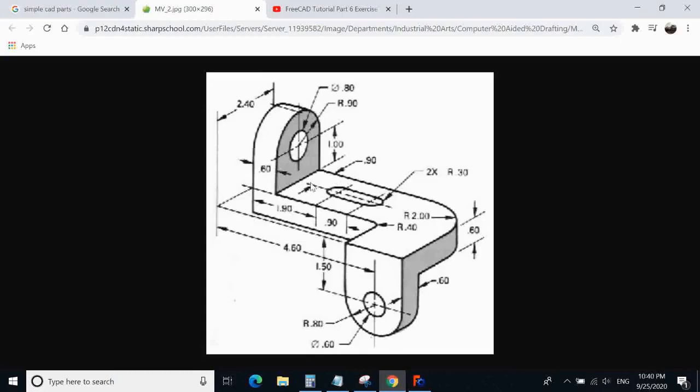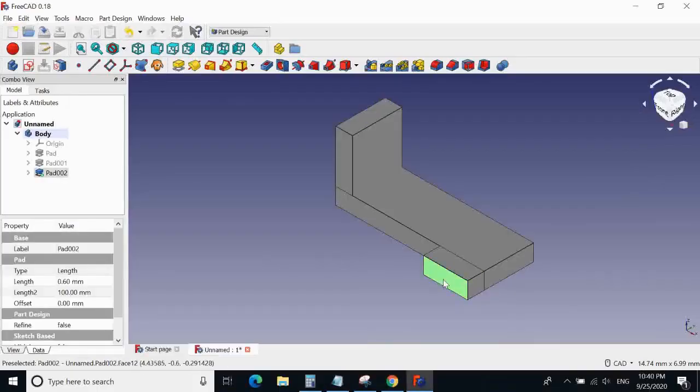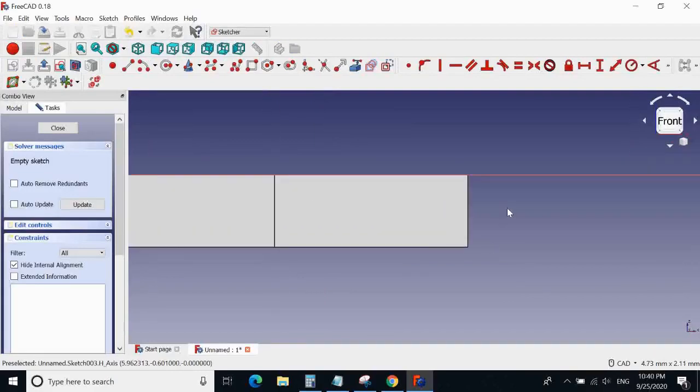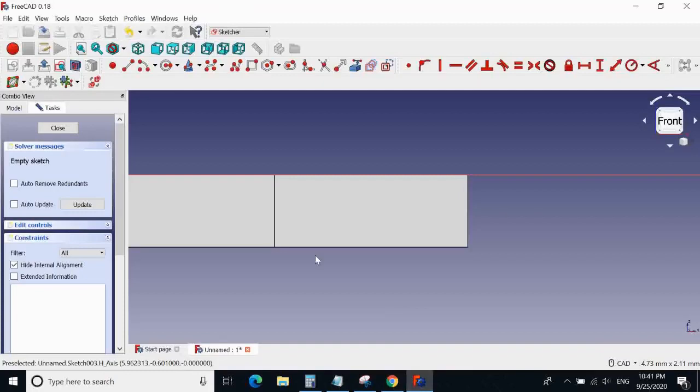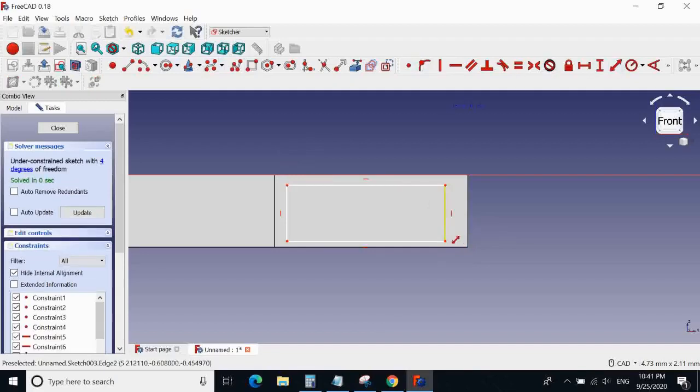So see how it's sort of taking shape? It's not perfect, but it's getting there. Okay, continue on building the parts piece by piece. Now I have to create 1.5 towards the center plus radius 0.8. So 1.5 plus 0.8 will give us 2.3. So we go back to here, make this distance, before we forget, 2.3.